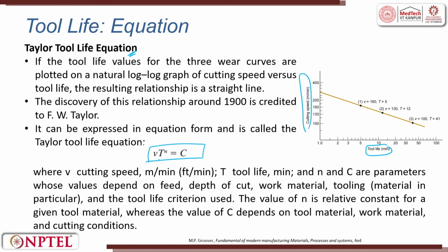With this equation, I can figure out at what velocity what will be the tool life time, and C is a constant between workpiece and tool. This equation was expressed by F.W. Taylor, and it is otherwise called Taylor's tool life equation.